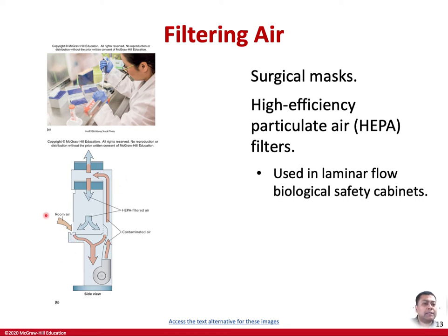In the schematic, you can see the environmental air is sucked in, and through a blower it is circulated through a HEPA filter, and the HEPA filtered air is pushed into the chamber. This creates a positive pressure in this air cabinet. So why do we call it a laminar airflow hood? Because this HEPA filtered air creates a positive pressure, nothing from the environment can come inside, even through the opening, because there is a positive pressure inside. It is also recirculated, and extra air can go outside into the environment through a HEPA filter as well.